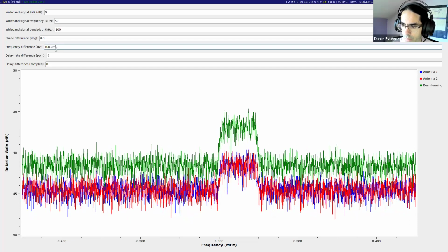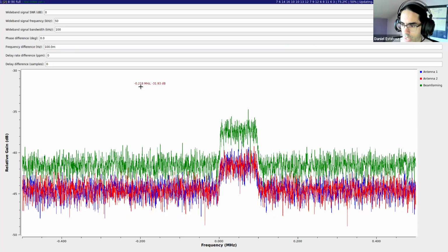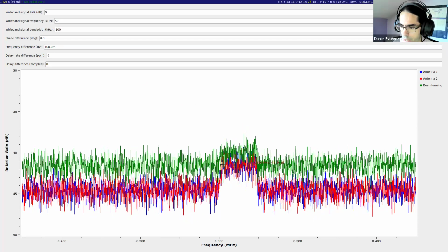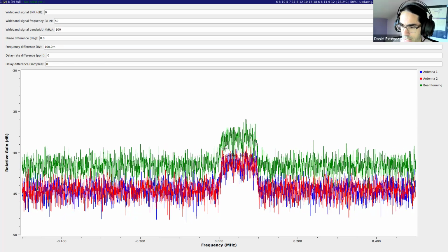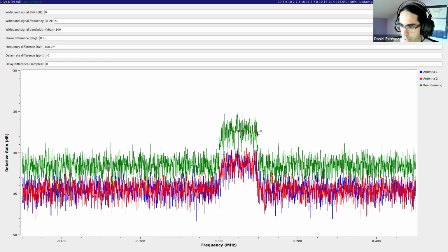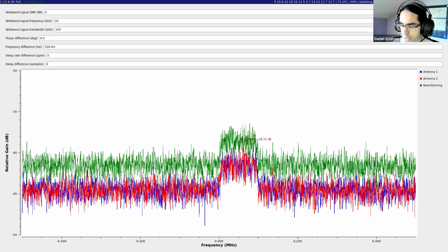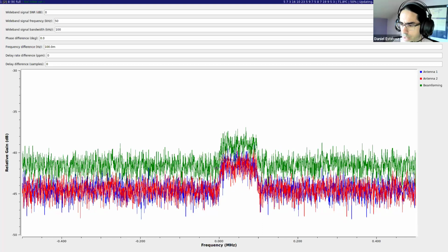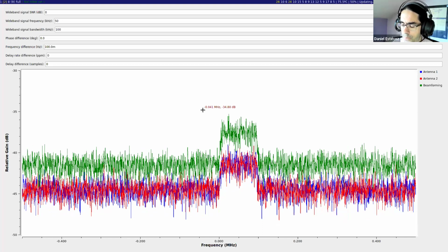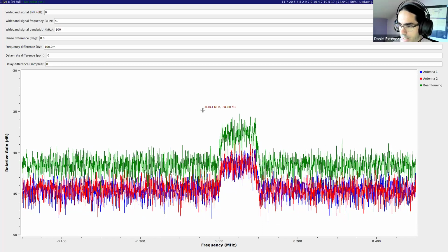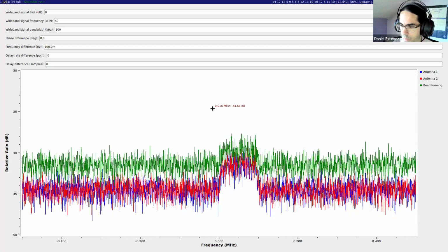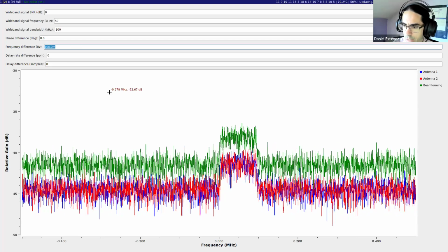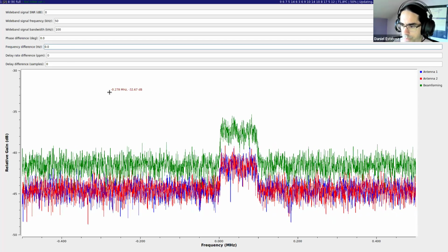So I press enter, and now what happens is the signal is decreasing. Now there's cancellation, so now the offset is 180 degrees. And again, the signal is increasing because now they have more or less the same phase. So this is how a frequency offset looks like. You have cancellation and addition of the signal changing over time. We can revert this to 0.